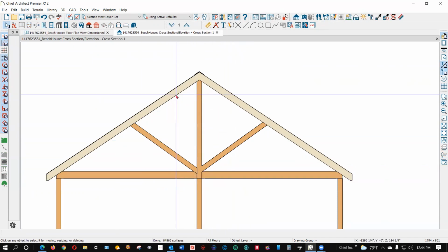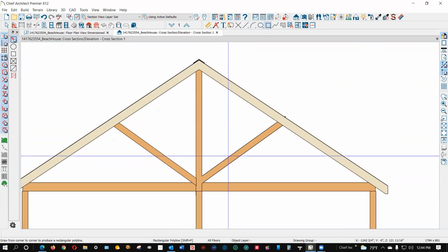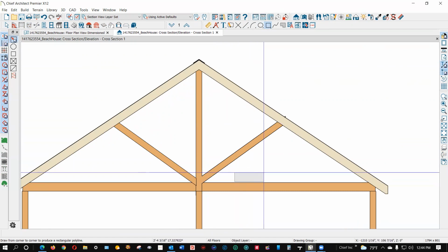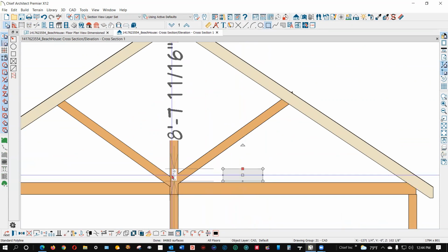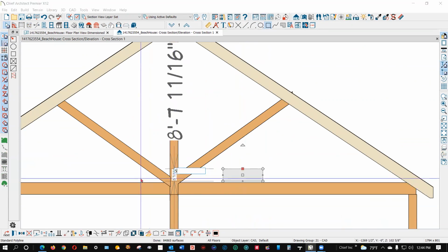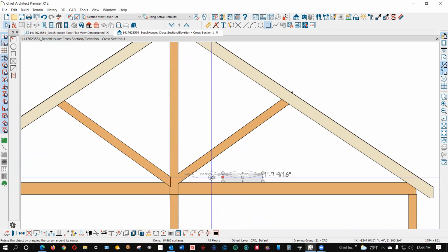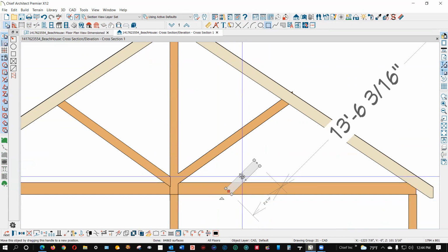Now with Polyline Solids, there's a couple of different ways to do that. You can just, in an elevation camera, draw a closed polyline. We'll set it to 5.5 inches. I'm going to rotate it to 45 degrees.